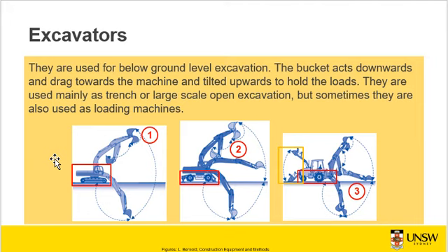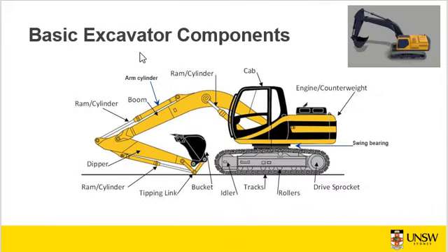It is best practice to use rubber pads when working on flexible pavements to prevent the steel tracks from eating up the road, and additional costs incurred for defect reparation. Right. So we will now look at the basic excavator components.